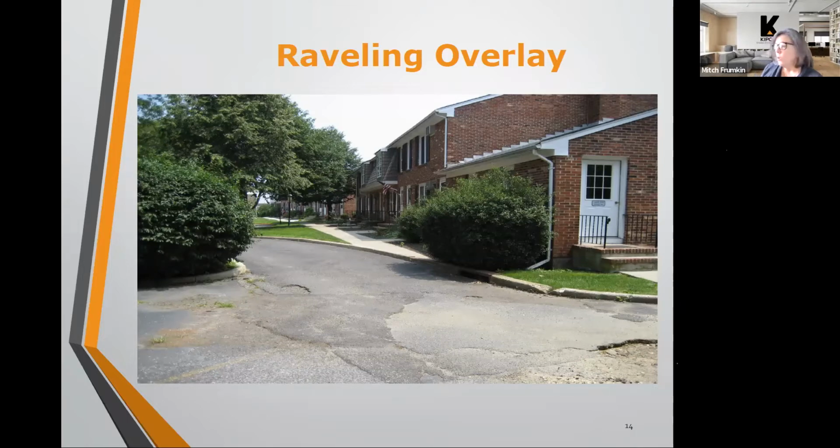I will tell you though, if you're planning a pavement project in the fall and we put together specs in the fall and then we have a pre-construction meeting in the spring, I always recommend that we walk through with the contractor and physically mark out with marking paint which curbs need to be removed, and that we agree on which curbs need to come out and be replaced. The reason we do that is because you've now gone through a winter between the specs and the work being done. So that curb quantity that's in the base bid may increase slightly if there was any further damage over the winter.